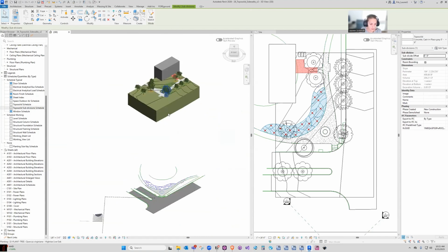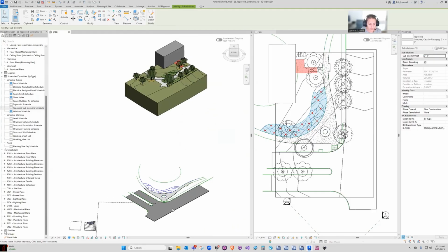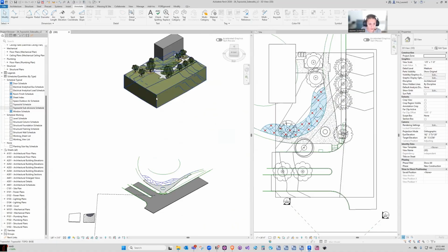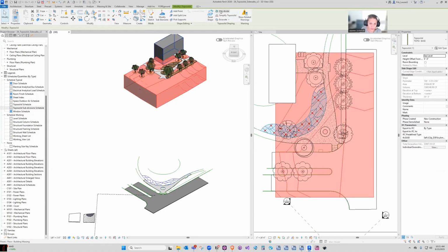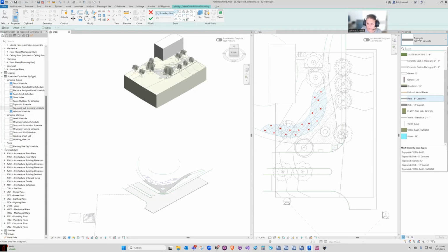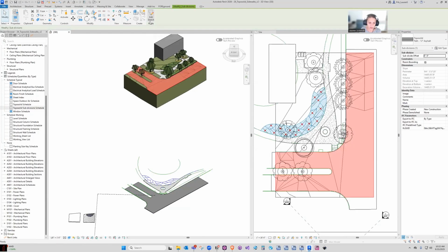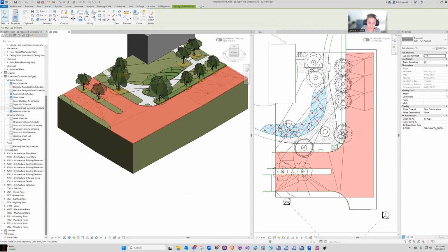I'm going to make a subdivision using this roadway. I'm not going to drape it, but I'm going to use this as an outline. So just to recap, I'm going to grab my base topo solid, subdivide it, use my asphalt, and then use my pick lines. I'm going to tab select my road outline. That's why I made that, as a quick method to get that on there. There we go.